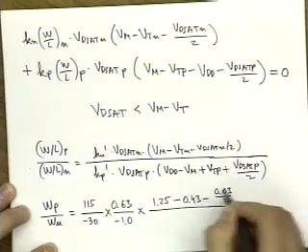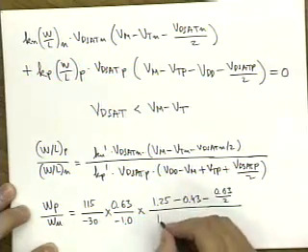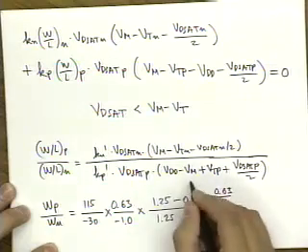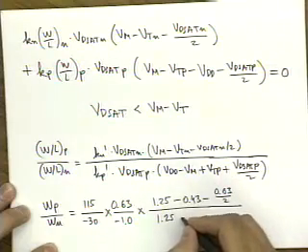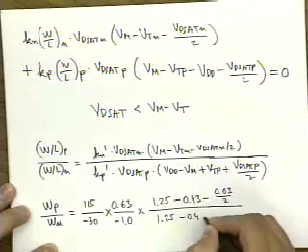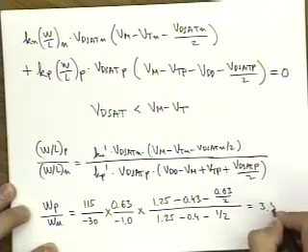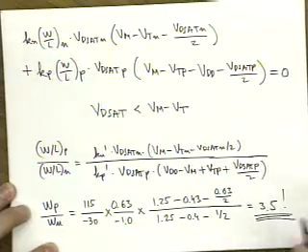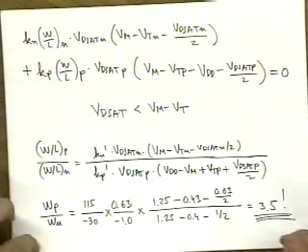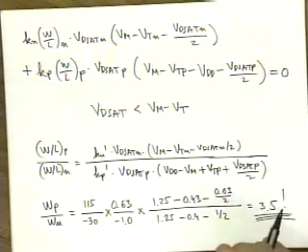You get these numbers from the table in the book. And then you have Vdd minus Vm, 1.25. Vtp is negative, so it's negative 0.4, and this is negative 1 over 2, and then you end up with 3.5 for symmetric characteristic. That's a huge number, right?